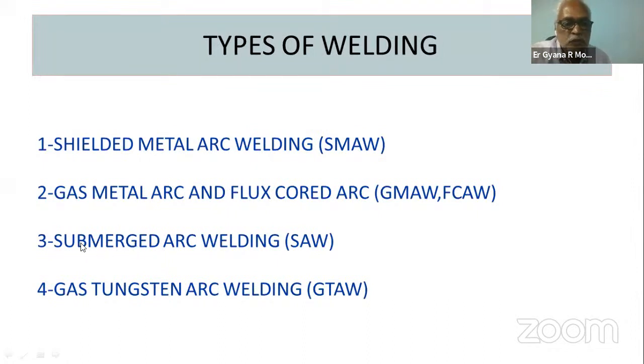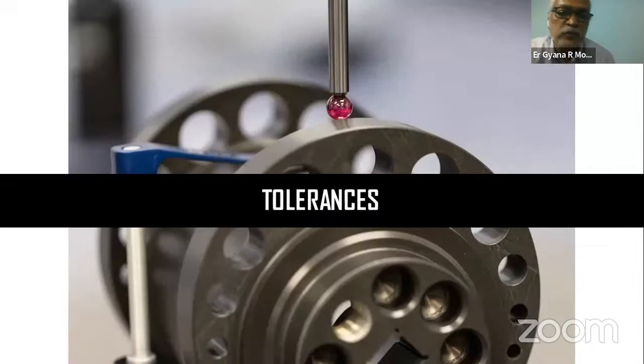It should not have any sort of acidic component, which can dilute the properties of stainless steel in the joint. So in case of stainless steel arc welding, which is relevant to our bridges, the wire that we should be using is normally of the parent material or a slight combination or different composition, but the flux has to be neutral so that we do not have any loss of composition because of the welding. And let's come to tolerances.